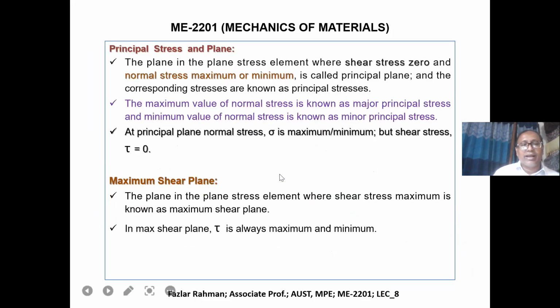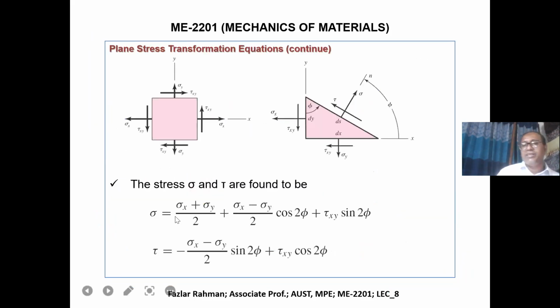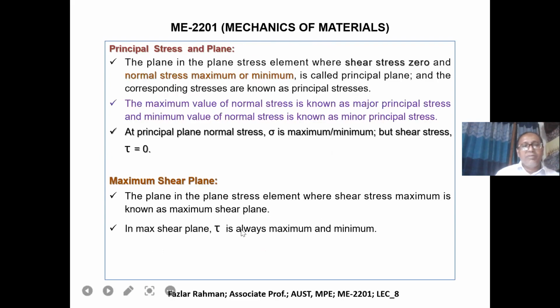substitute right over here, how many sigma you will get? You get 2 sigma, sigma 1, sigma 2. And you will see one value giving maximum, other one giving minimum. And those two angles, if you put in this equation, you'll see tau coming automatically 0. Okay, if it's not coming 0, that means you did some mistake. Similarly,